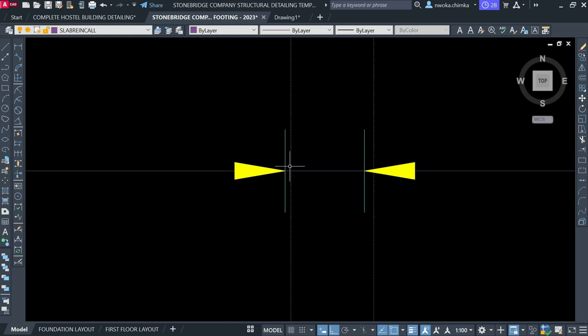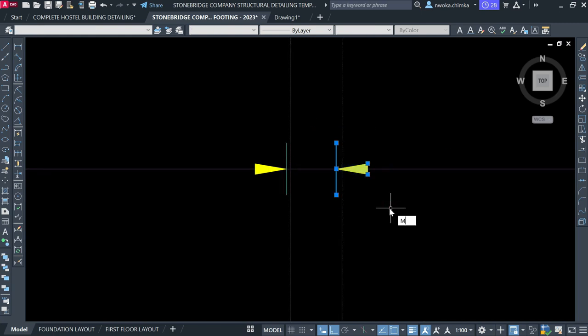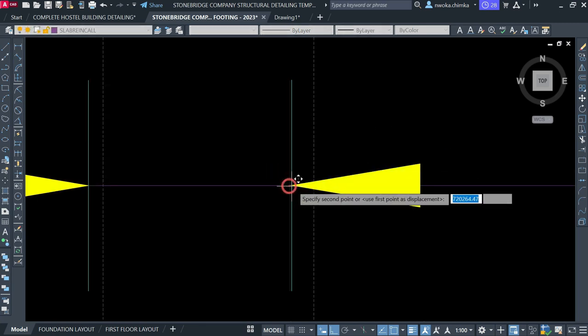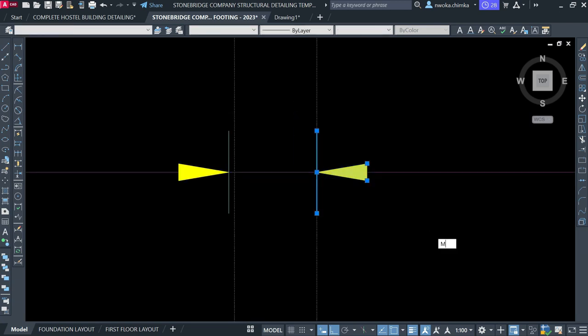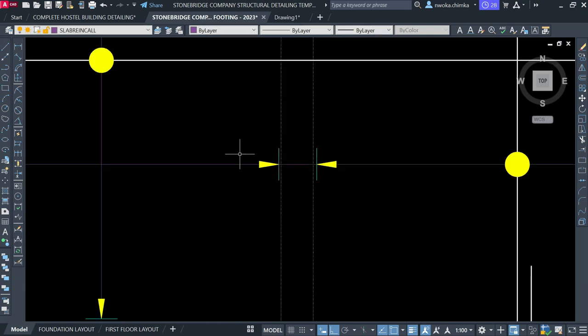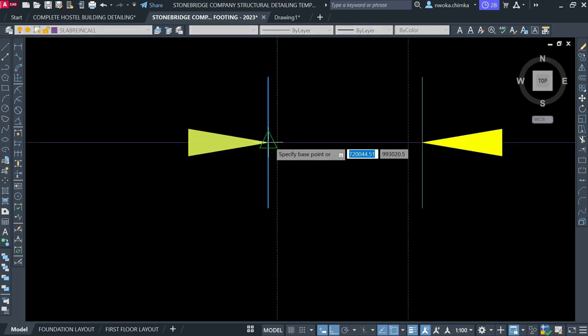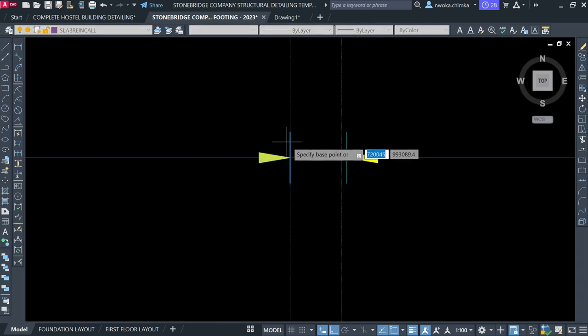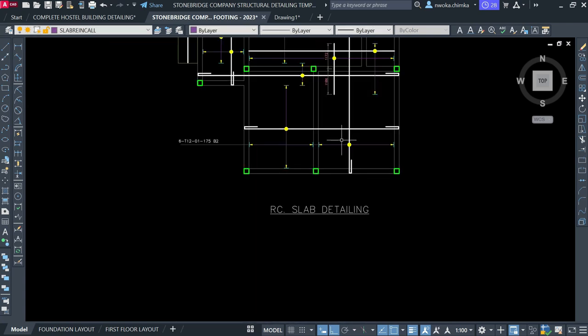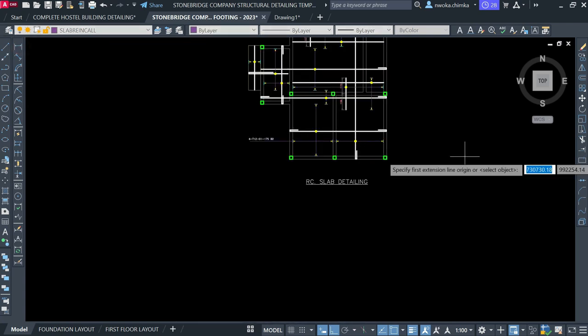Okay, that's fine. I'll now move here again, backward. Keep this here first of all, and then take my cover of reinforcement backward by 25, cover 25. I'll move this again first of all to the end, and then move it backward again by 25, which is the cover of concrete. 25, enter.